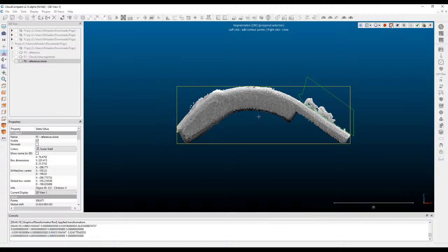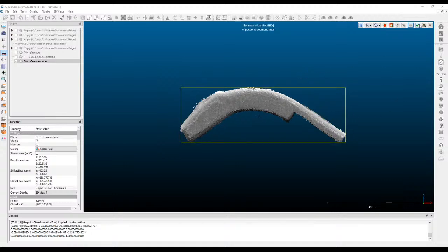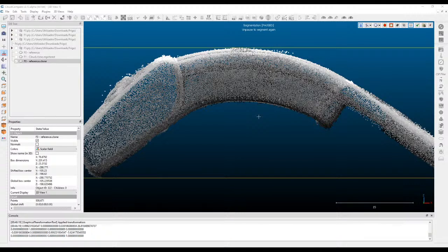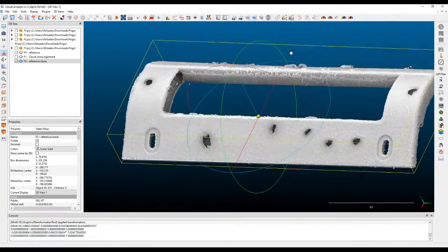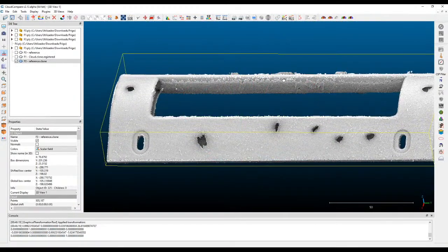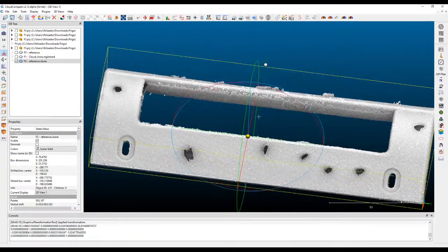There you go. So segment out. You can also remove these ones. Pause, select here, but these could probably be automatically removed with the noise removal that we'll see in a second. So segment out, let's confirm and delete hidden points, and there we go. There's a couple of blutac points there that we can probably just remove.